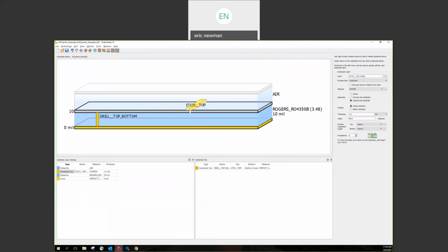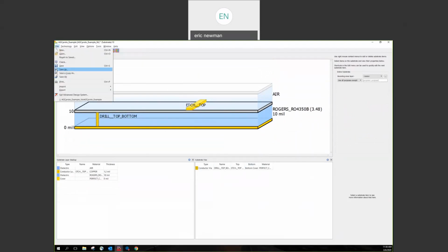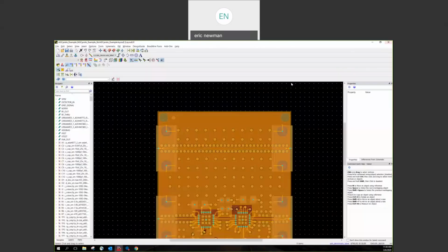In general, when doing these imports, you want to make sure that copper or whatever is assigned is the materials, the thicknesses are right, make sure everything came over properly, make sure your CAD engineer didn't get lazy about documenting some of the dimensions and material properties and such. Anyways, we're going to use this as a modified substrate. So I'm going to say save as cover. So this will be our simplified substrate for running some of our first EM simulations. Hit X.